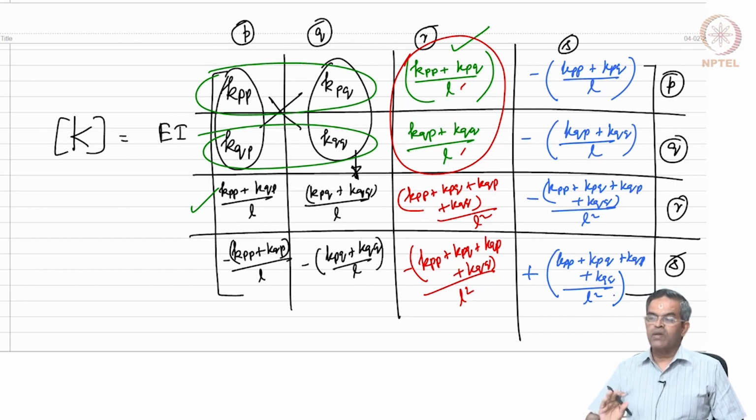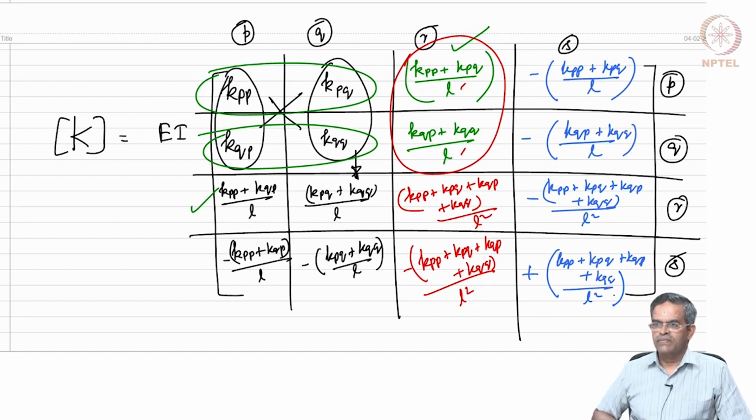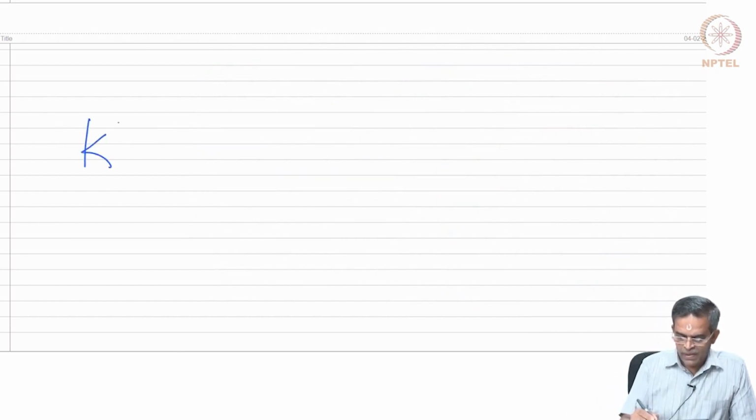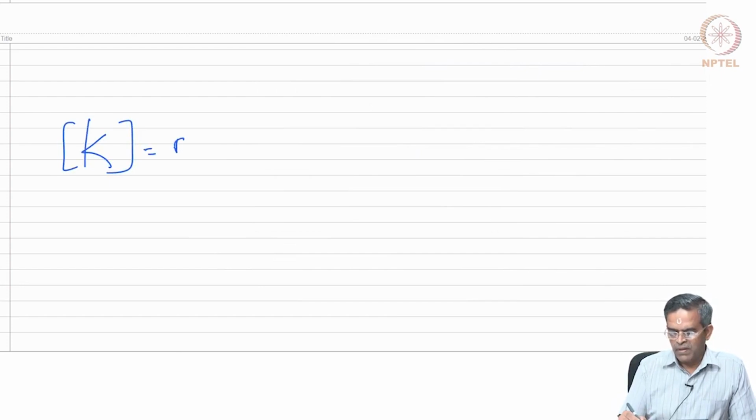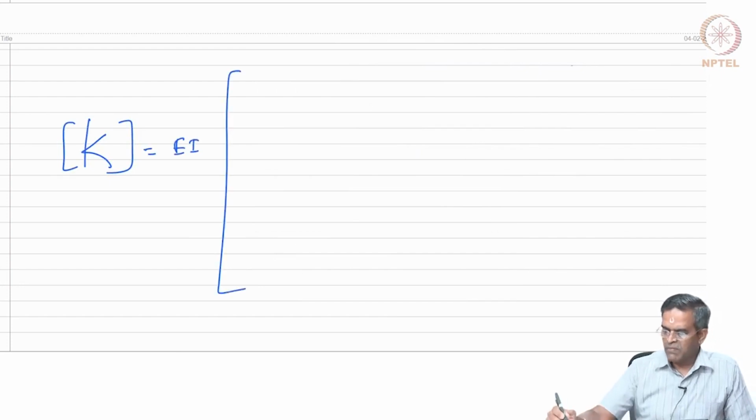Okay. So, I am following the same algorithm we used for this derivation. What we did is, instead of giving the rotations, we started finding this out using the flexibility method, and we also wrote this equation in the previous lecture, and we said that my K matrix for a simple fixed beam neglecting axial deformation is given by this.